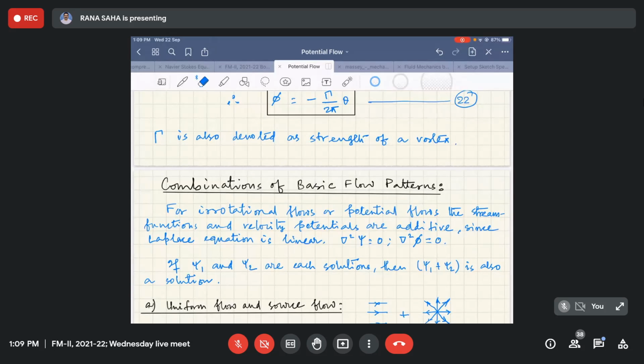If in a flow field, at a particular point, the flow velocity can be brought to zero, then at that point the static head and the dynamic head are converted into a total head, that is known as stagnation head, and that point is known as the stagnation point. So the important thing is that at the stagnation point the velocity of flow should be zero.